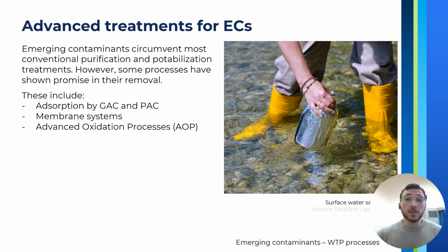Speaking of advanced treatments, we have introduced earlier that many emerging contaminants evade most conventional purification and potabilization treatments, and thus end up in drinking water as well as natural waters. There are, however, some processes which have shown significant promise in the removal of emerging contaminants from waters, and these include adsorption by GAC or PAC, or granular activated carbon and powdered activated carbon, membrane systems, and advanced oxidation processes, or AOPs, among which is included ozone treatment.